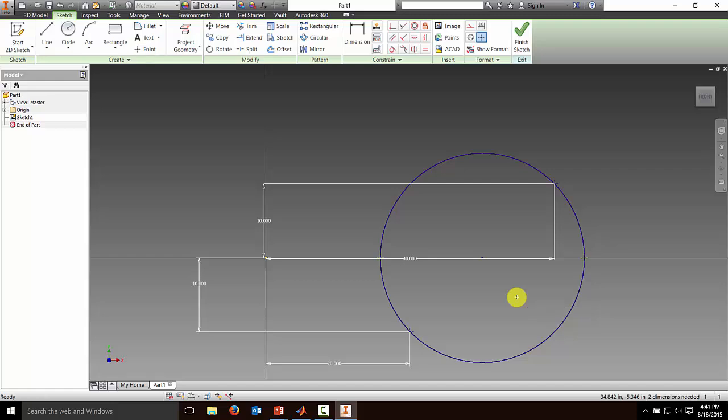And now we can draw circles. There's a lot of different ways to do it. I'm going to do it one way. I'll probably show you a different way in class, but whichever way works is fine with me. I'm going to take a circle and grab it until it connects to that point. And at this point, I'm going to go ahead and fully constrain this circle before I continue. So the first thing I want to do is make sure that the center is horizontal with the x-axis. And I also want to make sure that this circle is coincident with that origin.